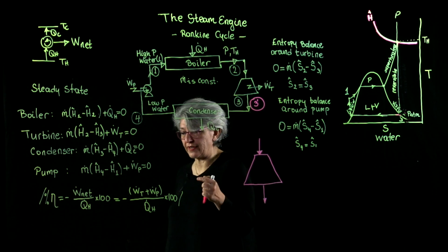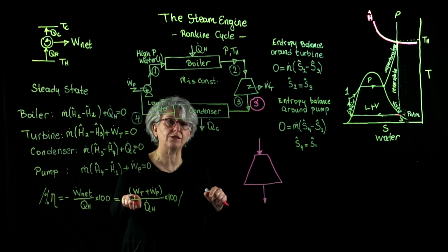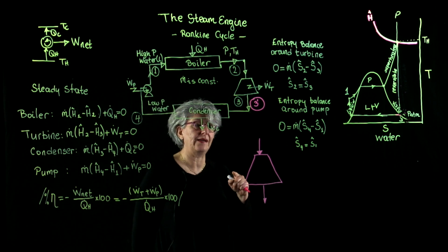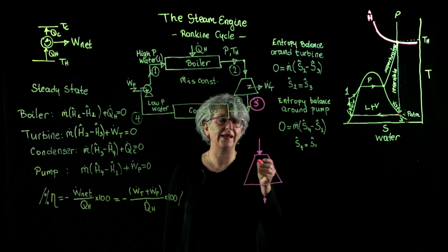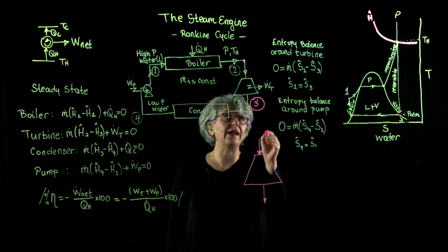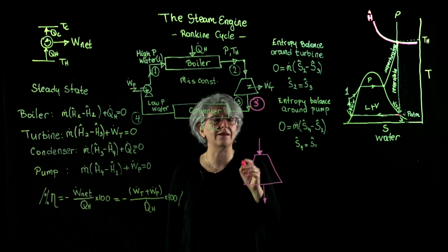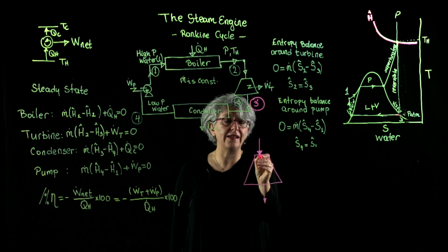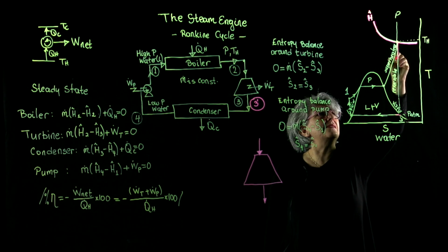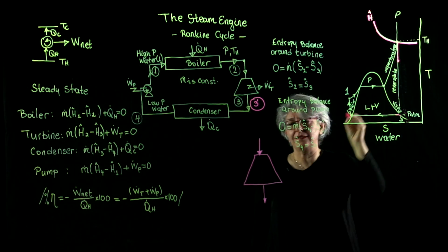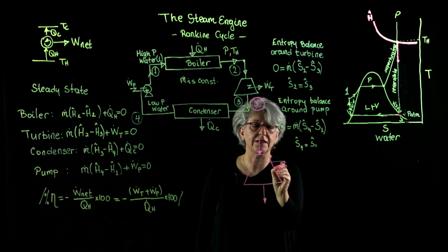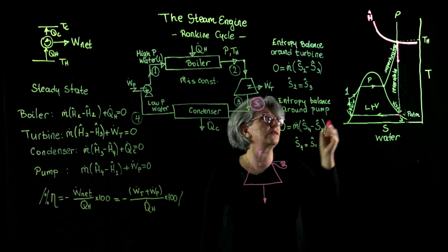The efficiency of your cycle depends on the amount of work that you obtain from the turbine, and you can maximize this by gradually adding heat to your turbine. Now, your steam entering at state 2 in this diagram may expand a little bit, and then we can take this steam, perform a heat exchange, and deliver it to the same point.